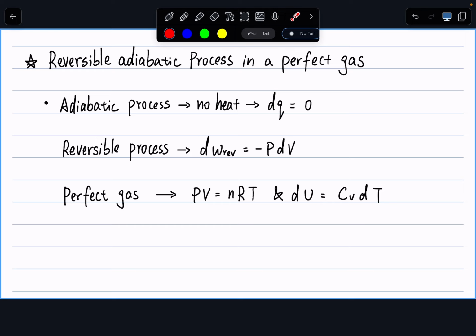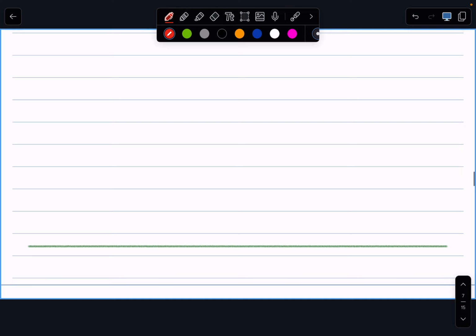But not one or the other. If it's an ideal gas but delta T wasn't 0, delta U would not necessarily be 0. For ideal gases, internal energy and enthalpy are only dependent on temperature. That's one of the properties of the ideal gas. Or the other way to put it, for an ideal gas, if my internal energy change is 0, my temperature change must be 0. If we go one more step back to the Joule-Thomson experiment, we're talking about a process where delta H is kept 0.